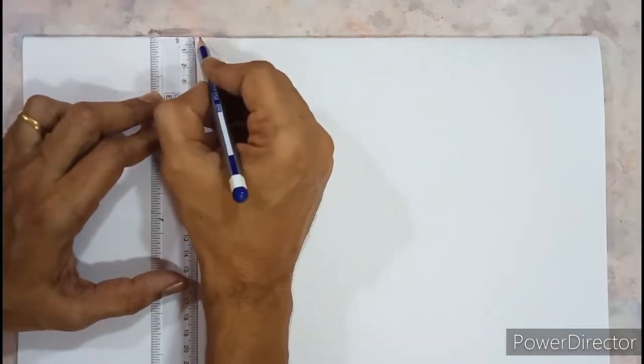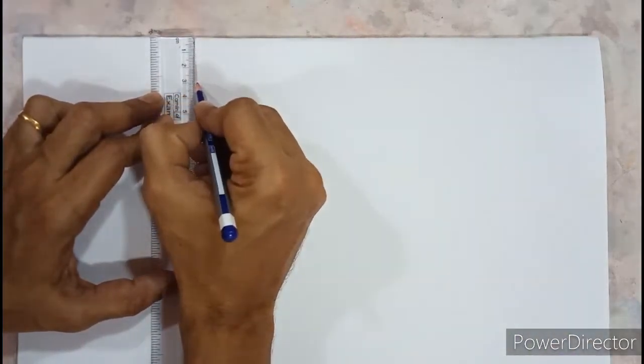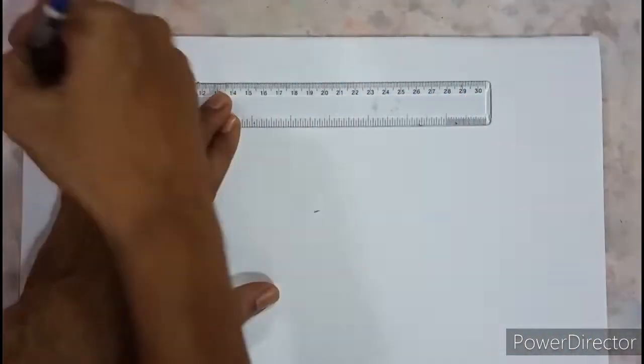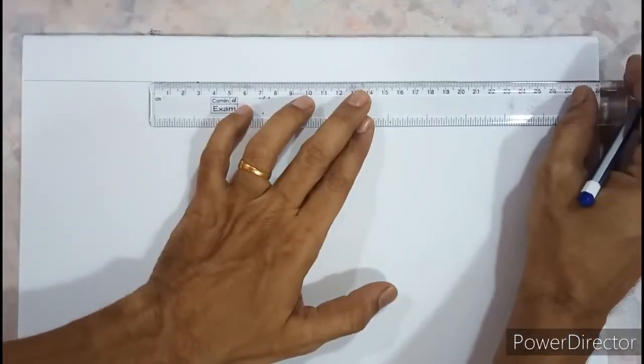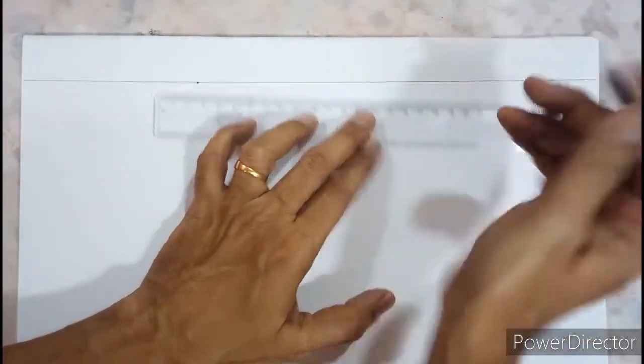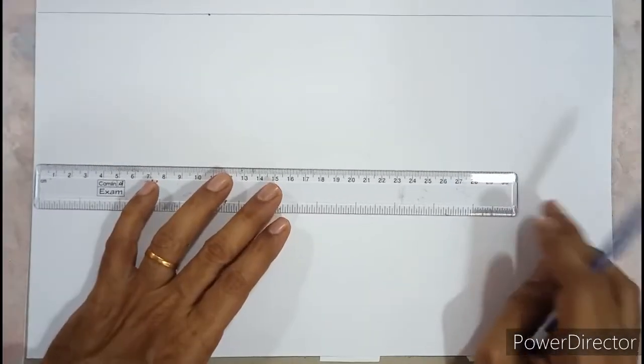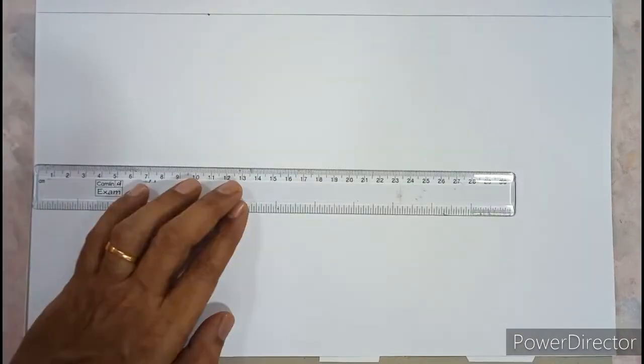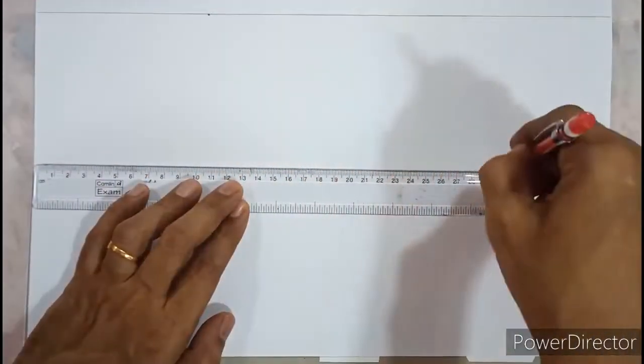What we'll do is, we'll mark 30 mm from the top edge of the paper and draw a horizontal line. Within this 30 mm margin, we'll copy down the question later on. We need to write the question within this area later. Next, in whatever space is left from this 30 mm till the bottom, approximately in the center, we need to draw a medium dark xy line. So let us draw a medium dark xy line throughout the page.